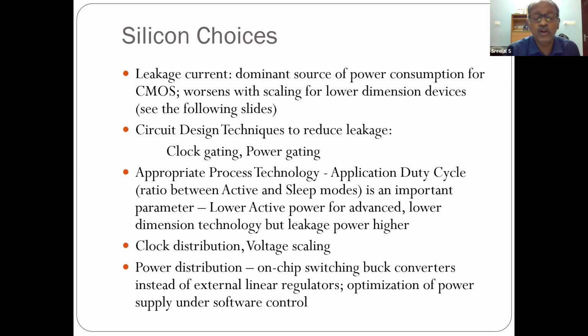So it basically doesn't do any activity. But if we turn on the mobile phone in the evening, we can see that some battery charge has drained away. So why does it happen? That is basically due to the leakage current of the circuit inside the mobile phone, which happens even if the mobile phone is in standby mode. So as we have seen in the case of the inverter also, that 2 transistor inverter, even though there is no static path for the current, there will be a small leakage current flowing from the power supply, and that will lead to the battery drain.